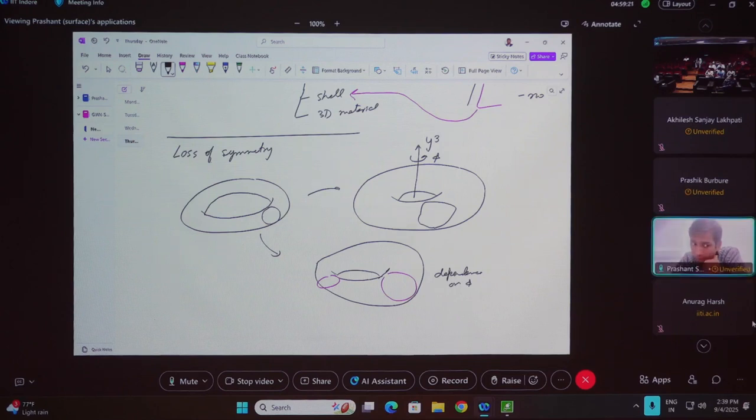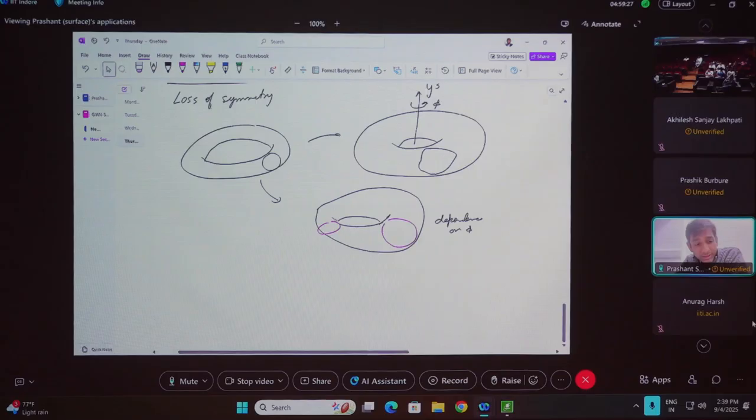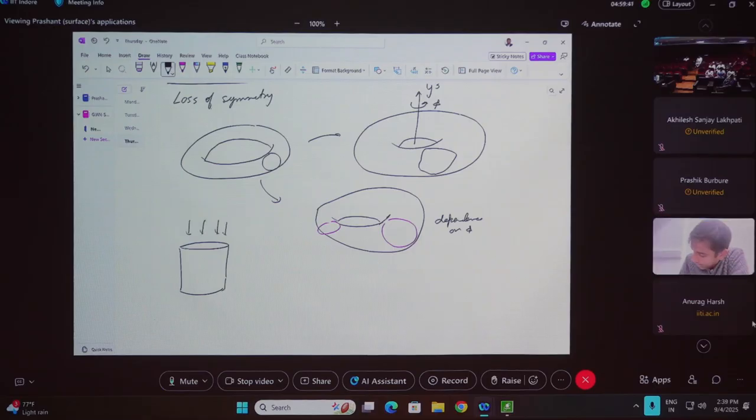And this happens to a lot of different structures that are symmetric. So beam buckling is very much like that. Or you might have a cylindrical shell. You might have seen this problem of shell buckling, where you have a cylindrical shell, you apply loading on the top, and it basically compresses, but then it develops these kinds of wrinkles.